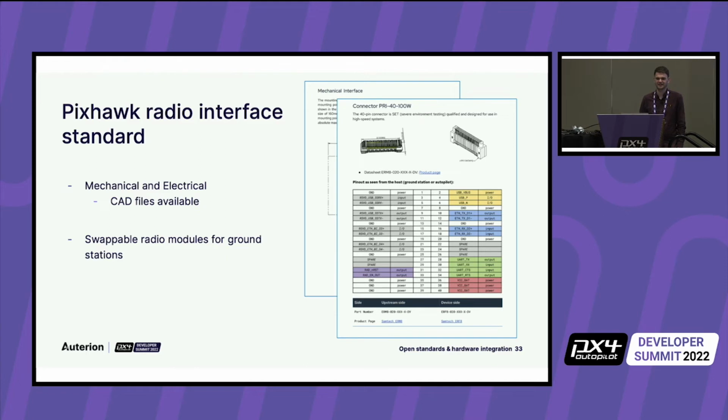But it's not in the Pixhawk docs, that's for sure. PX4s all have that same RC input, and the drivers and receivers are just UART driver receivers. I think it just uses the GPIO on PX4.